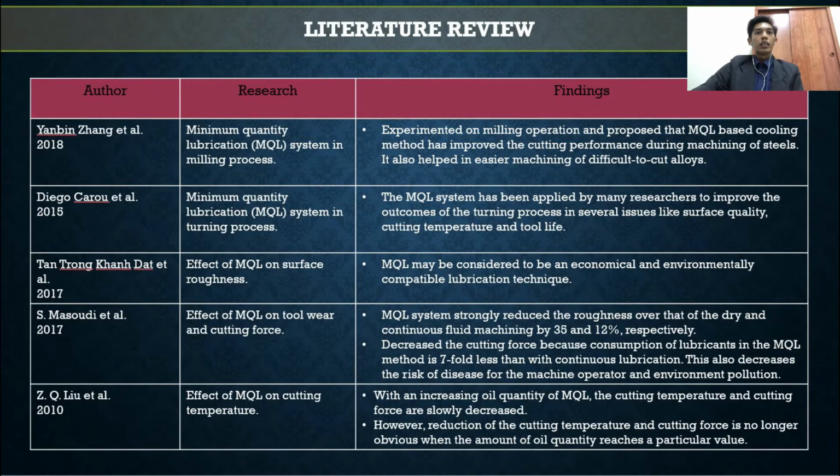ZQ Liu et al. 2010, in his research on the effect of MQL on cutting temperature, found that with an increasing quantity of MQL, the cutting temperature and cutting force slowly decrease.